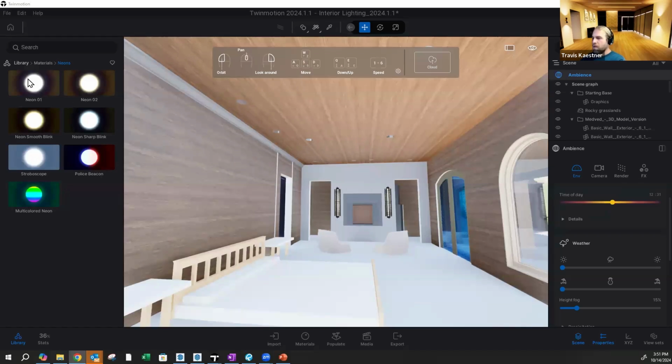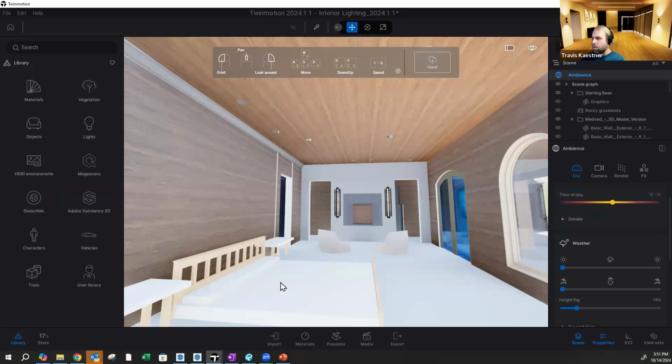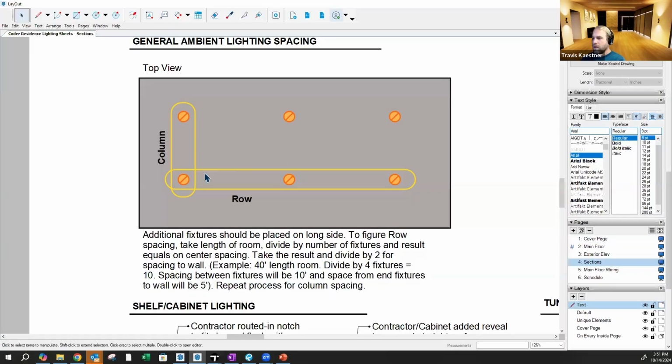Let's see here. If I'm looking at this space and I want to lay it out, a typical way we show a space on our drawings is a top-down view of, say, a room. Say it's laid out with 6 can lights, 3 by 2. Usually the higher quantity goes on the longer side of the room, because this one's longer, and then the shorter side, so we're making it even. And then how to lay them out. If you're doing a typical lighting layout, this isn't really designed.